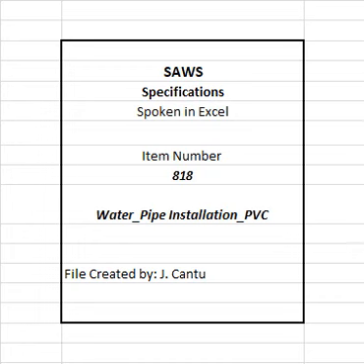Submit a hydrostatic leak testing plan which includes equipment, pump, water meter, pressure regulating valve, pressure gauges, etc., water handling procedures, supply and disposal, sequence and schedule by test section, and pressure test data. 2. Certifications of calibration, approved testing laboratory certificate if pressure gauge for hydrostatic test has been previously used. If pressure gauge is new, no certificate is required.